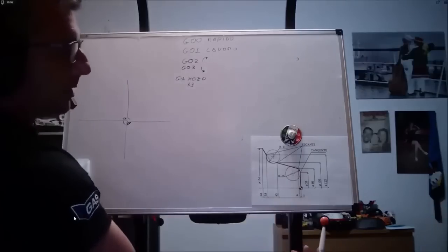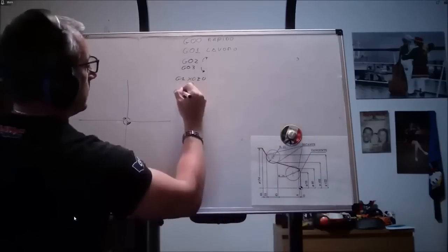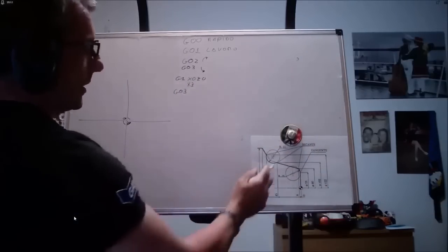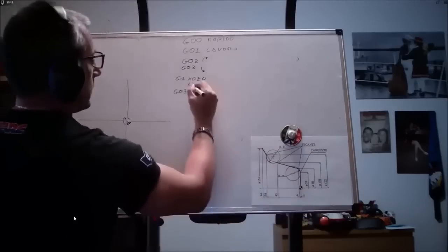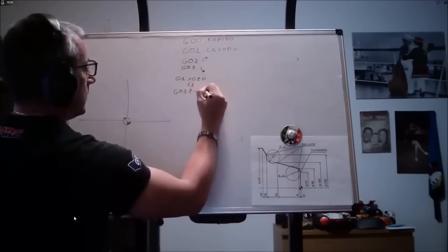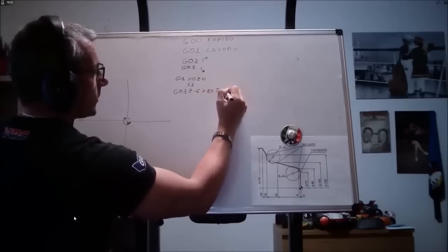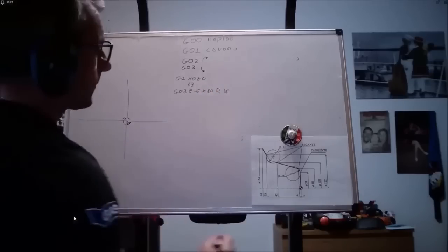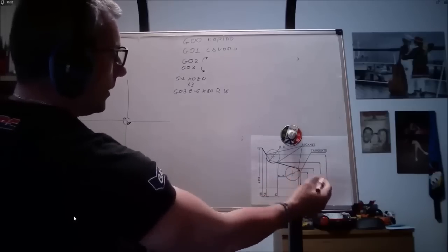Then we have a radius to traverse counterclockwise, G03, Z6, X80, and here we put our R16. Then we insert two coordinates that take us to Z45, X102.